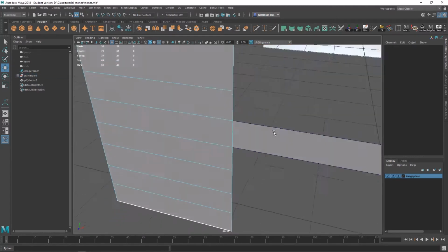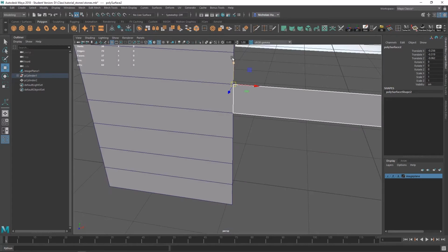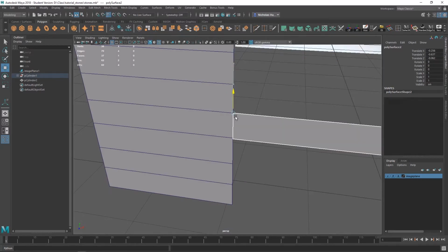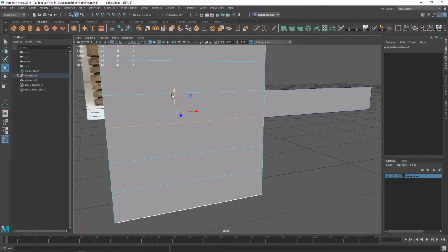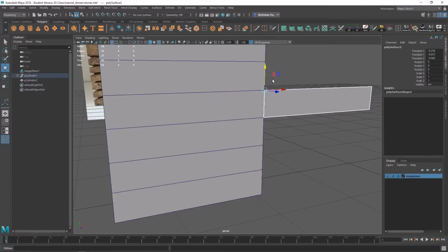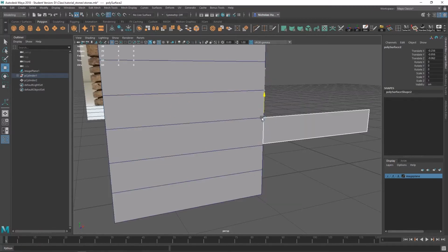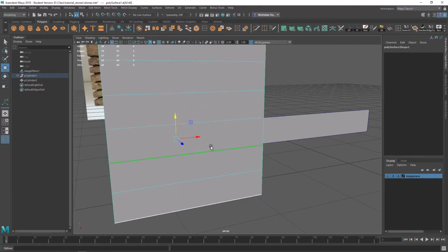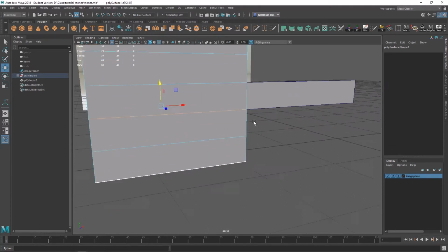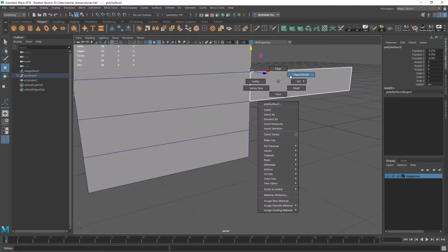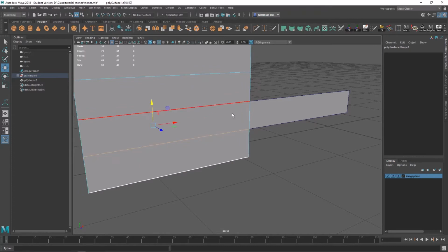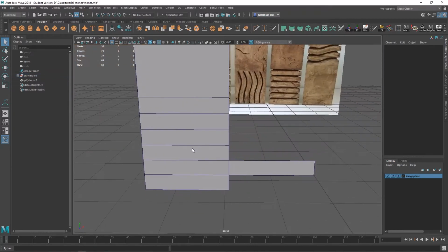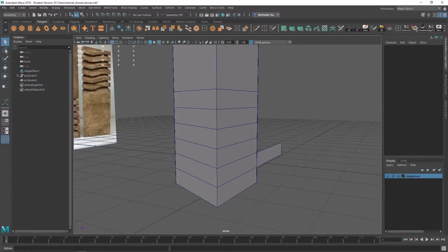Then you want to click your measuring piece right here. Same deal, V, hold down, it'll go down there. Click this edge. Make sure that this one's highlighted, hold down V, middle mouse, it'll snap. Go back to object mode, V, just drag it down, back to edge, and we're just going to measure all these to this width here. Okay, now these are all perfectly the same width.